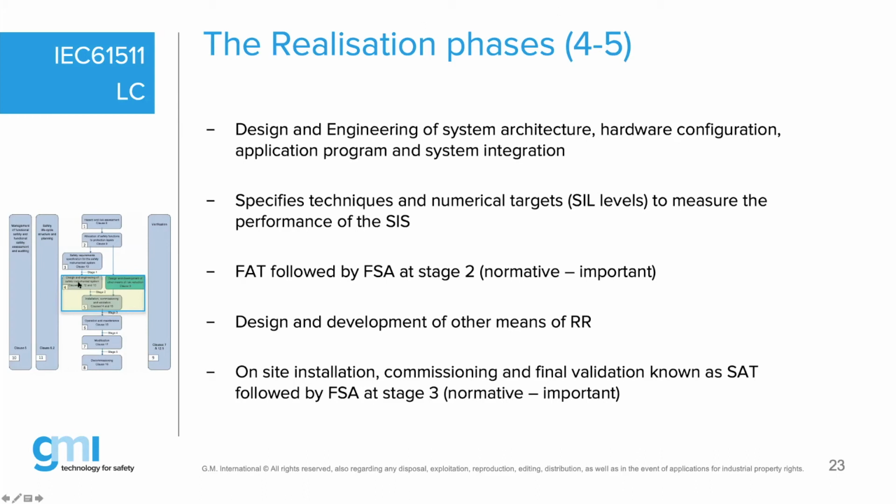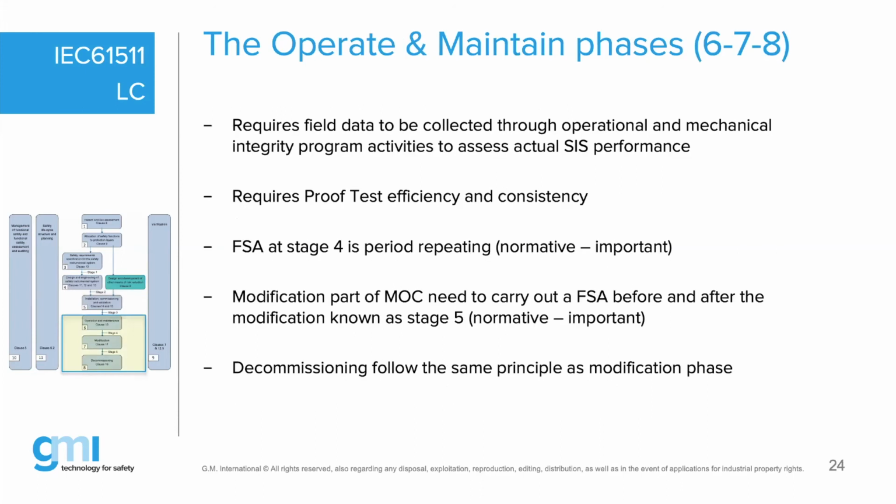That means it makes sense to do stage 1, but after having done the FAT or during the FAT, honestly speaking, that's what we call the FAT witness test. And that's where the assessments, stage 2, are normative and also, again, very important. Then you go on site, and before you introduce the hazard in the production unit, stage number 3 is again normative and is again very important. Mr. End User should not start up before the expert judgment gives him the allowance to start up, after having seen evidence and made the judgment that the system is suitable to reduce the risk on site.